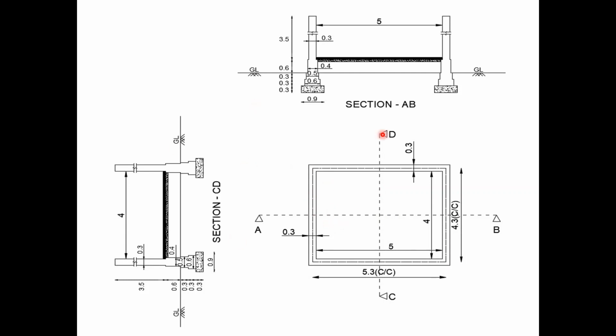In any project, the very first thing we have to do is the marking, and then go with the excavation. In this case, if we observe clearly, if I drop a center line for this section, let me mark a center line here, this center line remains the same for the wall as well as the plinth, as well as the first footing, second footing, and also for the PCC concreting. The center line remains the same for all the cases.